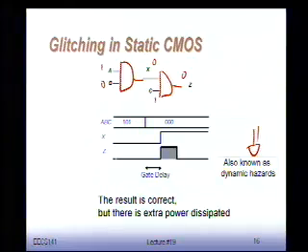Then I change my primary inputs, from 1 this goes to 0, and this goes to 0 simultaneously. What's happening? Well, if this goes to 0, 0, there goes my theory. It could be a NOR function. Probably is. Yeah, because it worked initially, but then from the time I look at my second transition, it doesn't work anymore. So suppose I put a NOR gate here. This node here, 0, 0, this is going to go to 1. Right?